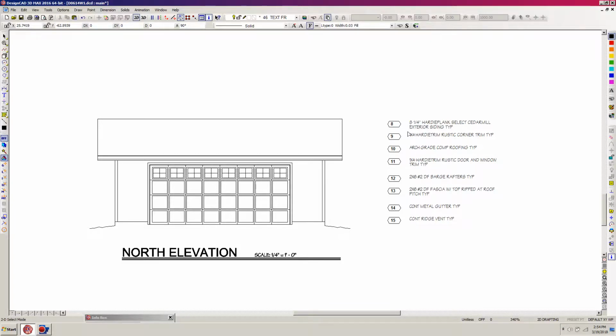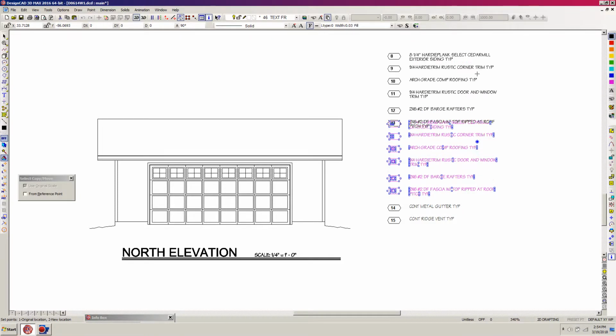One of the things that I want to do, for example, is to align the continuous metal gutter up here with the actual gutter. So I'm just going to take these, select this whole group here, and go to my handle, gravity move, hit M, and just arrow up, kind of out of the way here, a little bit.